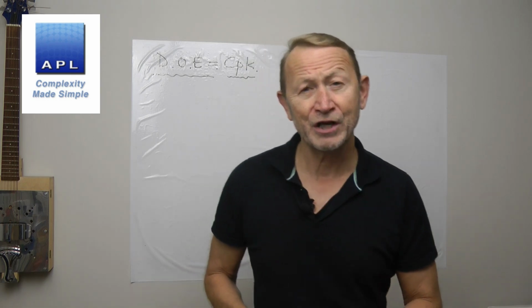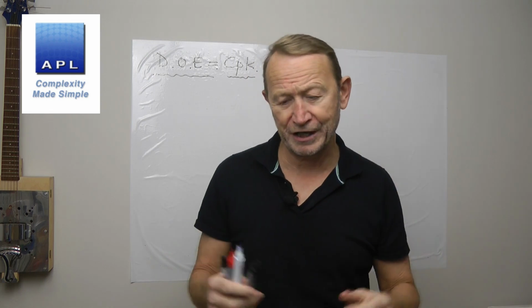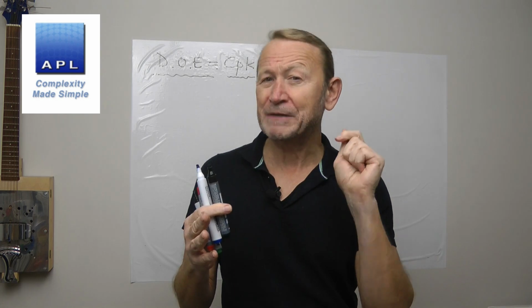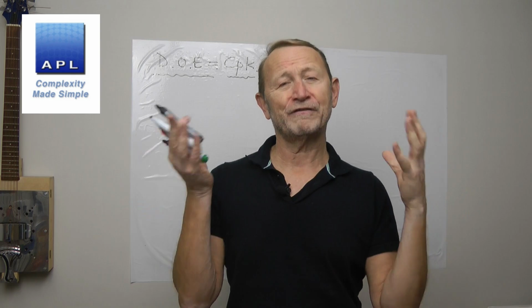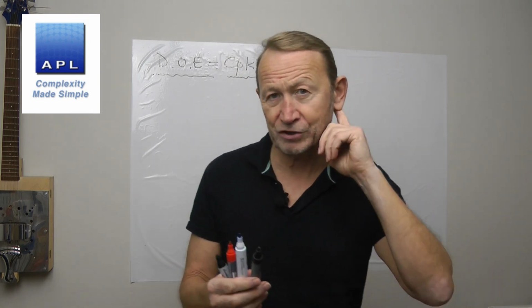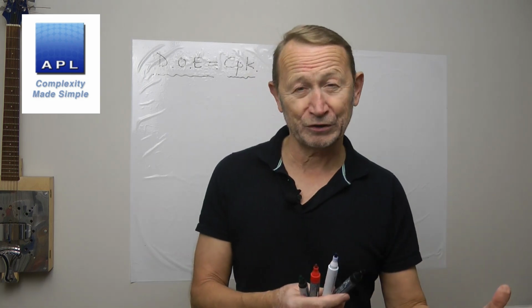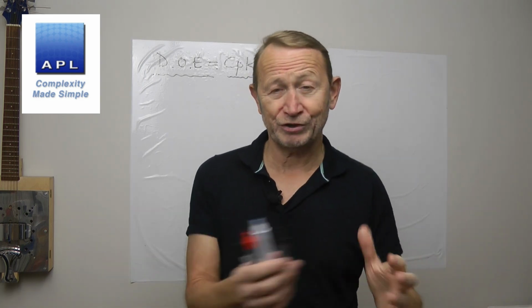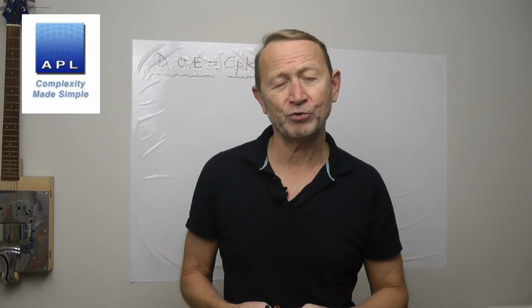So let's get into this. What we have is a DOE. It happens to be a Taguchi L12 screening DOE. So you're going to see me model with the L12. Now I have to say, modeling with the L12 isn't something I would recommend, but this particular client, this is real data, they want to try and save some time. So we've said, let's do the model with the L12. If the model works, brilliant, we don't have to do the full factorial.